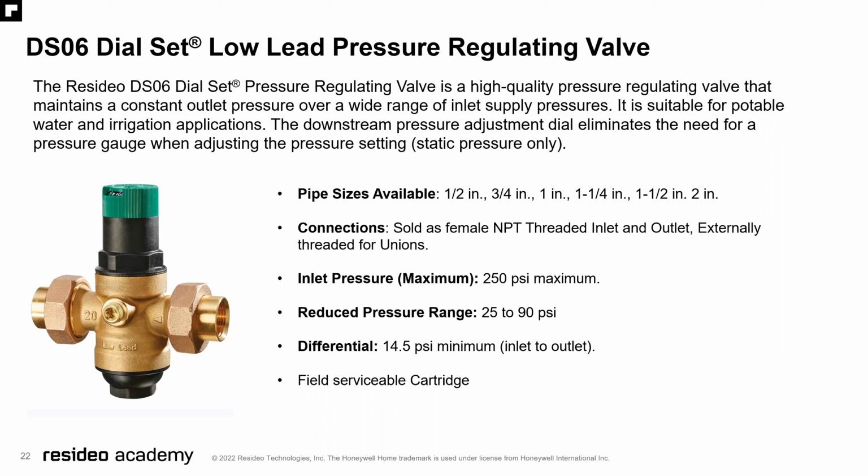It'll handle up to 250 PSI max, and it should be able to reduce that to 25 to 90 PSI with a differential of 14.5 PSI minimum inlet to outlet. And it does have a field serviceable cartridge.